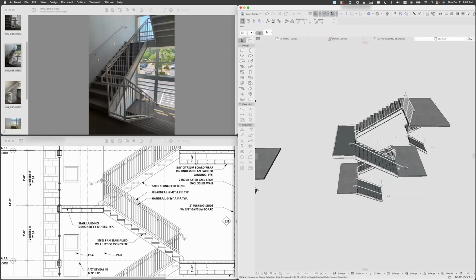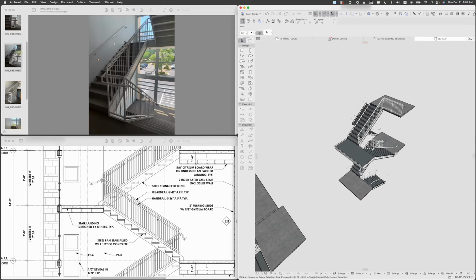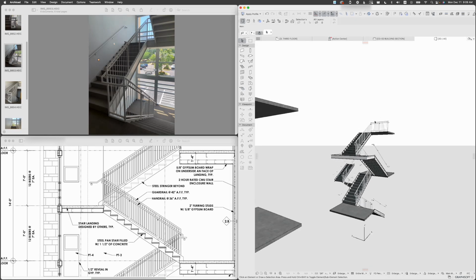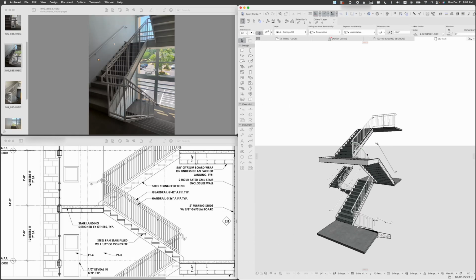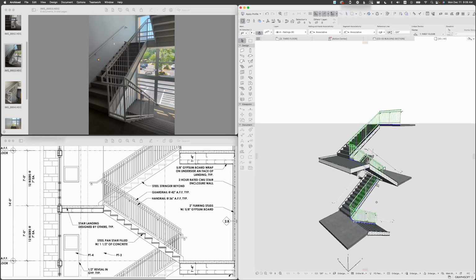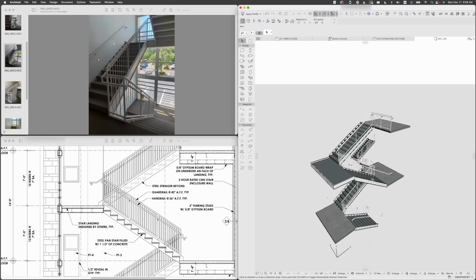That was it. I think probably we could still try to generate just one railing, trying to snap to all of this in 3D, all of the stairs, instead of having a couple of segments. So now how many elements do we have? We have one here, we have one here. We only have 2 elements. I think it's probably the correct way of doing it, because in plan you cannot snap to multiple floors, so you would probably do that in 3D, but it gets complicated, which is probably still doable.